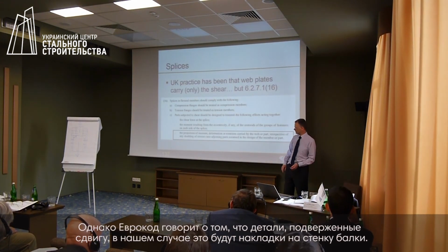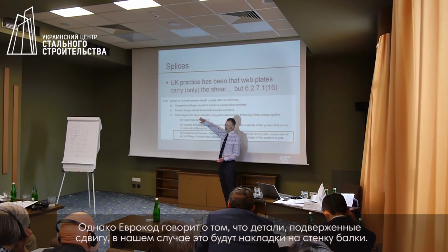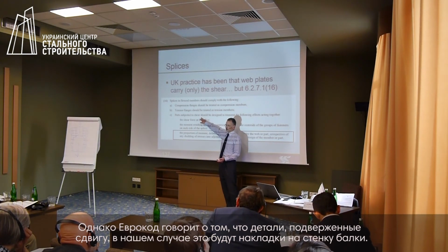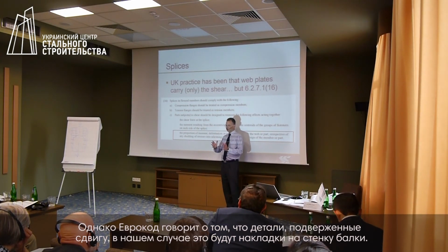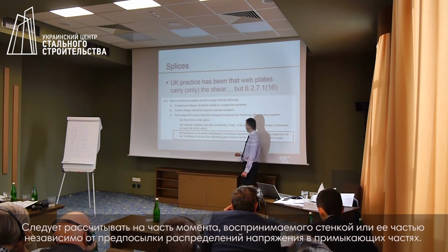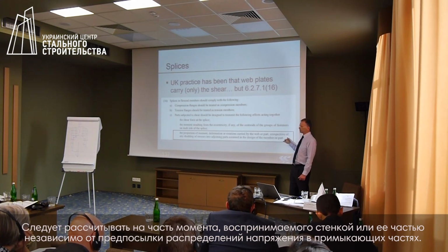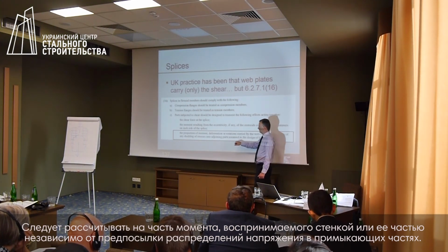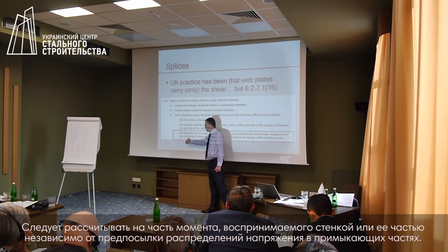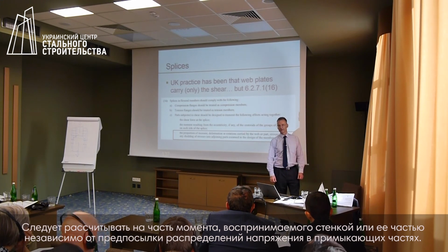The Eurocode, however, says, and I will read this in English, that the parts subject to shear, so that would be the web cover plates, they must carry the proportion of moment carried by the web, irrespective of any shedding of stress into adjoining parts.